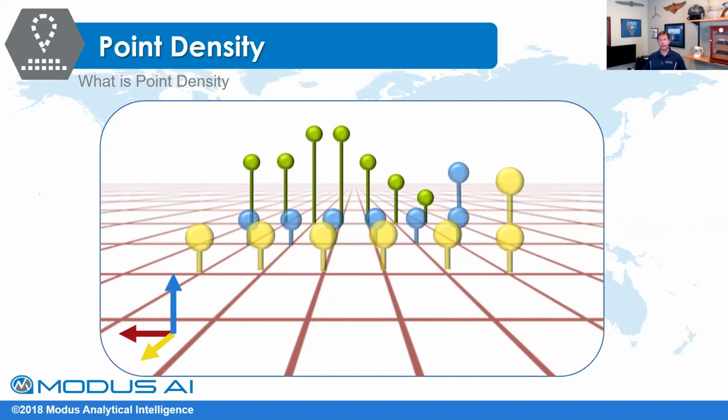And that's why LiDAR data is so flexible, because you can strip stuff out of it. If you get the wrong boresight, you can actually run an algorithm and correct it. But what you're looking at in point cloud data is a slew of discrete points that are fused together. So it's vastly different than what you see in photogrammetry.